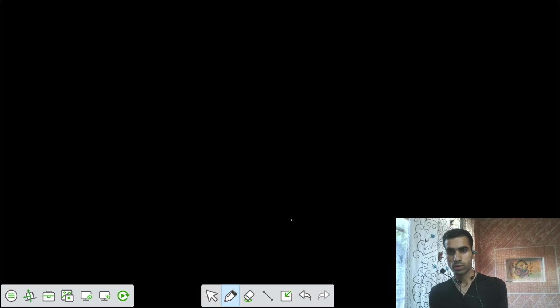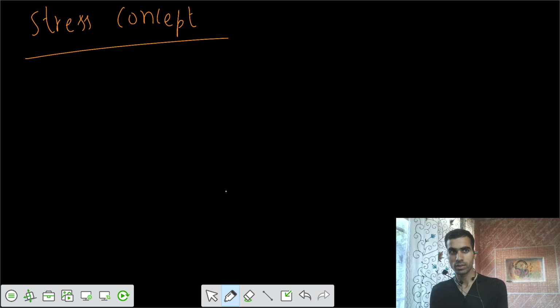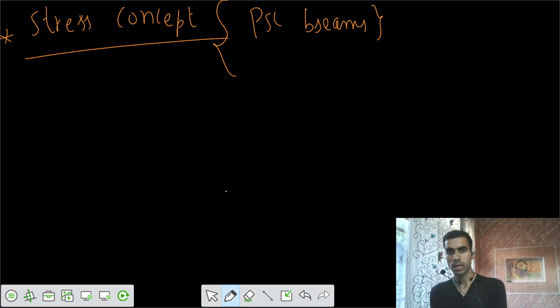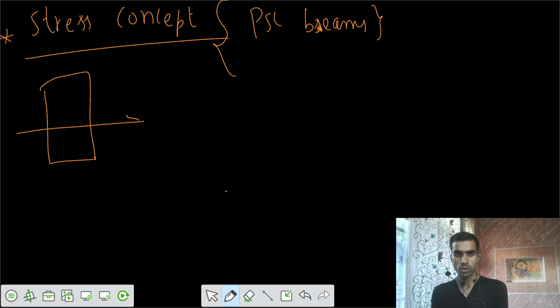This lecture is about the stress concept. This is the first method to calculate the stresses in the pre-stressed concrete beam, the PSC beams. So it's saying that generally you are applying that moment, applying that pre-stress load at some eccentricity from the neutral axis.